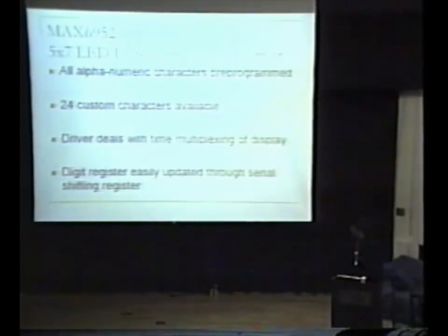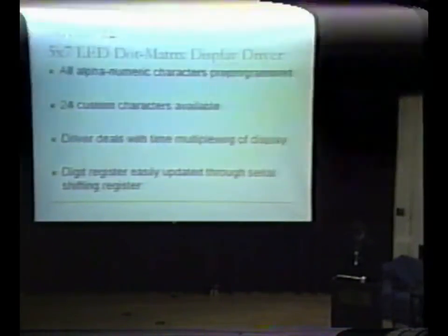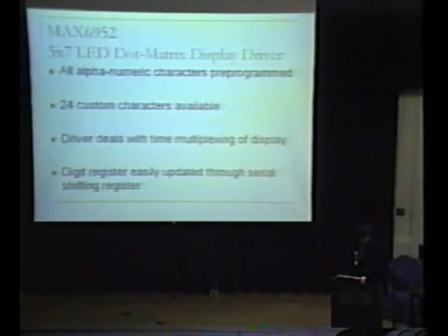The MAX6952 5x7 LED dot matrix display driver was used to control the 3-digit display. The driver provides all alphanumeric characters. It also has 24 programmable characters available in case you don't particularly care for one. The driver also deals with any time multiplexing that would have been needed for the display. And the driver also has its own digit registers, which you can store the characters in and are updated through a serial shift register.